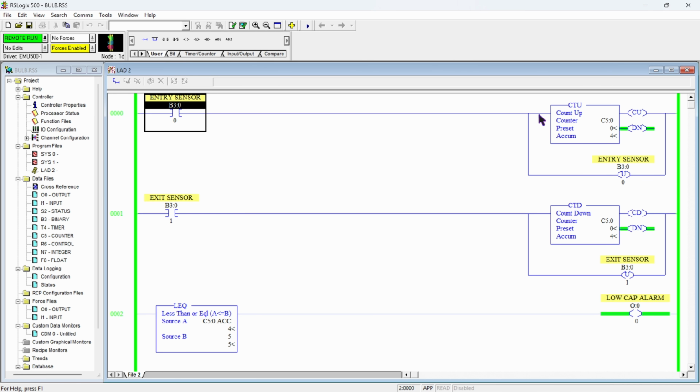And while the signal is going inside the counter, it is also going down here to this unlatch instruction, so that I do not have to go here and untoggle this binary bit. So this is the simple reason behind this unlatch instruction.